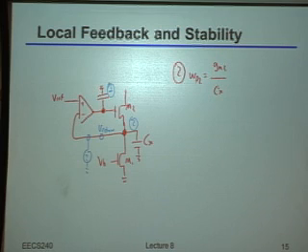Yeah, okay, you said it should be near the FT, right? And indeed, that's right, because at least if you do things properly, then the CX should largely just be dominated by the transistor's parasitics itself, right? It's never really going to be exactly FT, because there's always, I've got 2 junctions here, I've got another gate over there. But to zero order, indeed, it should be pretty close to the FT of the device.